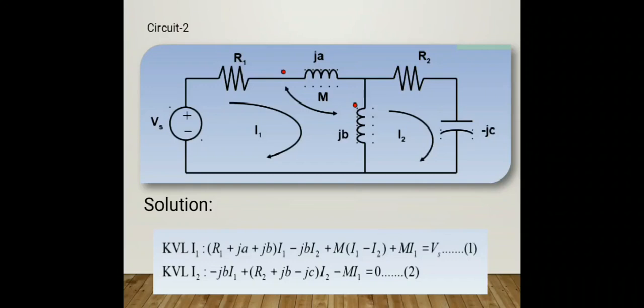If it is positive or negative, we must check at that place. The I1 current enters both coils, so it is positive. For LB, the I1 current entering LA creates a mutual inductance, so with I1 and both currents entering, it is positive.